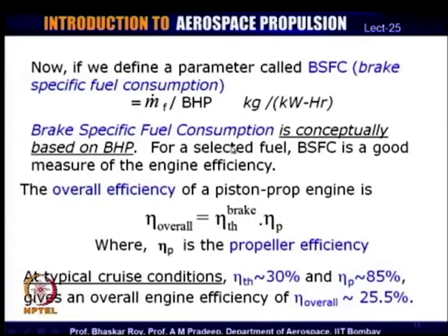Now, brake specific fuel consumption is conceptually based on the BHP. Conceptually you can also have an indicated specific fuel consumption, where instead of BHP you use IHP, but as I mentioned, the more useful one is the brake specific fuel consumption. So, when we say BSFC, we are talking about the utility of the fuel in terms of the brake horsepower, the final horsepower that is available from the engine.